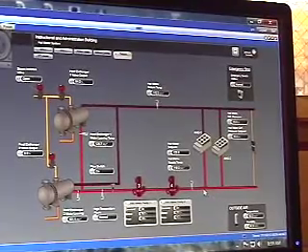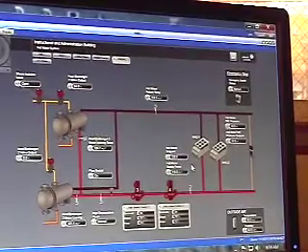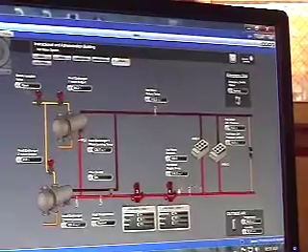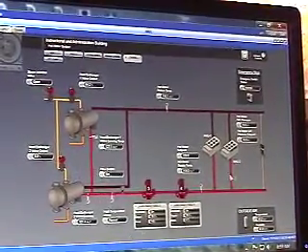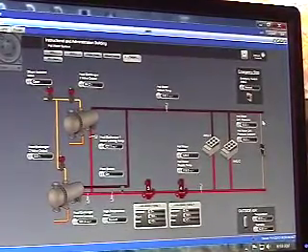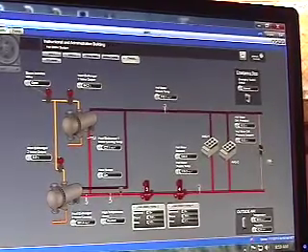Here we're trying to maintain, looks like just 120 right now. This does reset based off outside air temperature. This right here, hot water supply temperature, is your controlling sensor for these heat exchangers. Through your coils, this is your DP. Hot water DP is located on the 3rd floor. I'll show it on our as-built, but that's the location of the hot water DP.